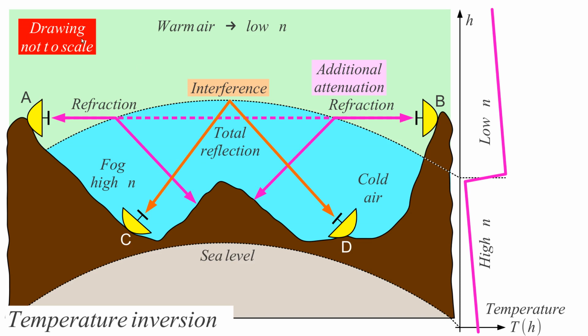If we have total reflection here, then we may get a connection between these two antennas that otherwise would be shielded by this small mountain in between. So we may have dropouts of some radio links that before operated correctly, and we may get new links that mainly cause interference, which only happen when we have total reflection at this boundary.